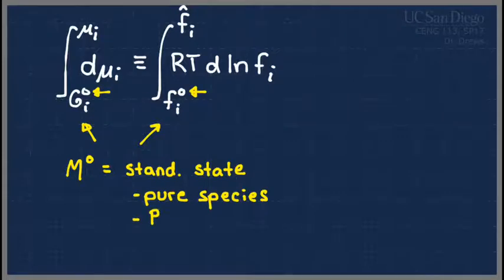It's always at a pressure of 1 bar, and we have a special symbol for that, which is P with a circle on it. Be really careful about that one. Even within chemical engineering, there are two standard pressures that are often used. One is 1 bar and one is 1 atm. They're almost identical, right? If you look at the conversion factor between 1 bar and 1 atm, they're really, really close. But if you're doing a fairly precise calculation, the difference there can throw you off quite a bit.